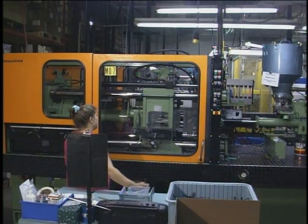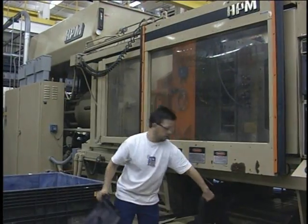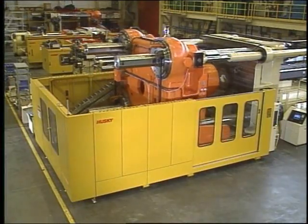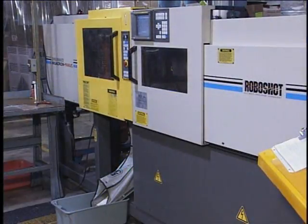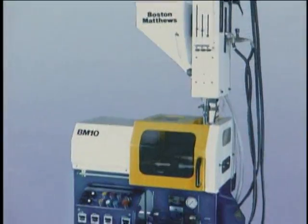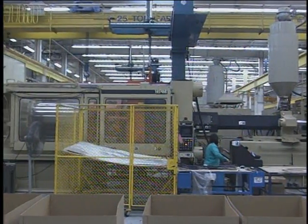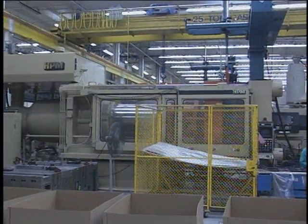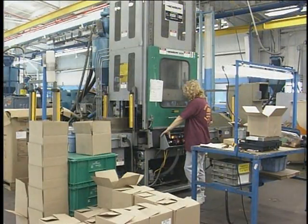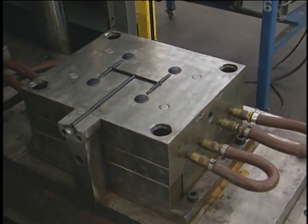There are a variety of injection molding machines in use today. The vast majority of these machines are hydraulically actuated and have 3 platens. But newer styles, such as 2-platen injection molding machines and electric injection molding machines, are now gaining market acceptance. Injection molding machines range in size and complexity from desk-size units up to machines the size of a small house. Most injection molding machines are horizontally oriented, but vertically oriented molding machines are available. These vertical machines are primarily used for insert molding.